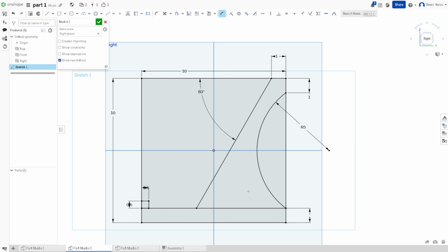Okay, so we have some space here that I don't like. So we are gonna again move this line here, but these lines are not parallel, and I don't like things when they are not perfect. So in the top right corner you have tools to modify these things, and one of them is called parallel, and you can add this line and this line, and it's gonna be parallel. Depending on which line you fixed, the other one is gonna get parallel to that one. And the other thing we can do is again go to 3-point arc. First let's just see the distance between these two. Let's say 1 centimeter, why not?